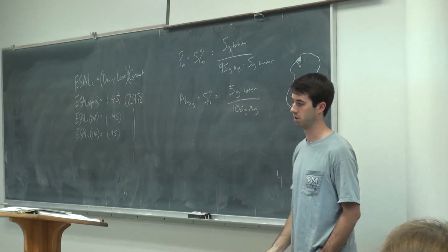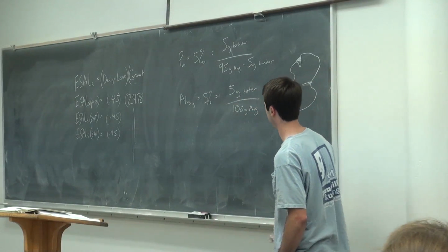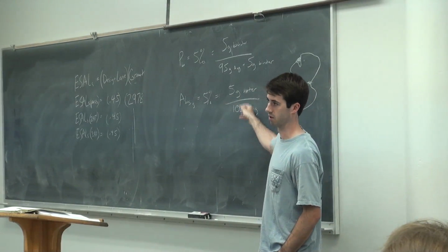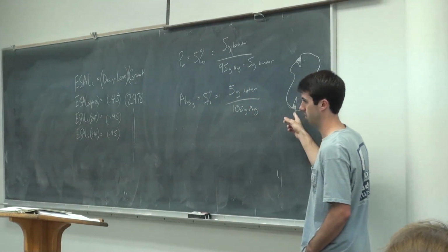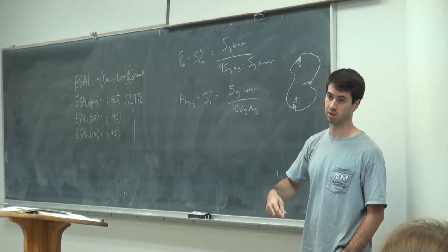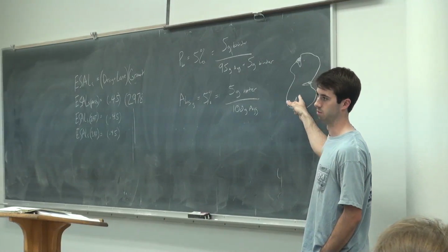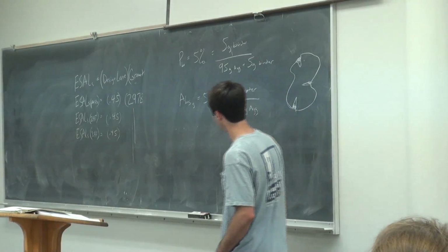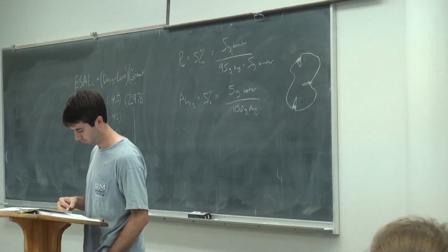You probably don't have no need to know that, but it's of the aggregate, it's not of the total mix now. So if you say we had 1% binder absorbed of the 5%, it doesn't mean that 4% is effective. It means that 1% of the rock weight is absorbed. So keep that in mind.